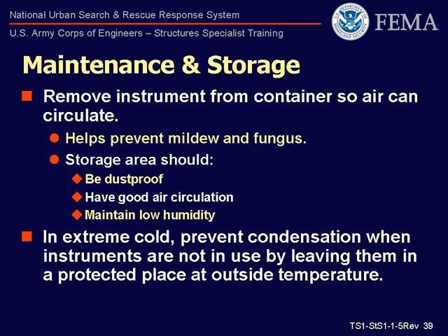Good practice when bringing the instrument back from a deployment or training exercise is to let it dry out a few days outside of its case. This helps to prevent mildew and fungus. But the storage area should be dust-proof, have good air circulation and low humidity to prevent further damage to the instrument. In extreme cold, don't take the instruments indoors during non-working periods, but leave them in a protected place at outside temperature. This will help to prevent condensation.